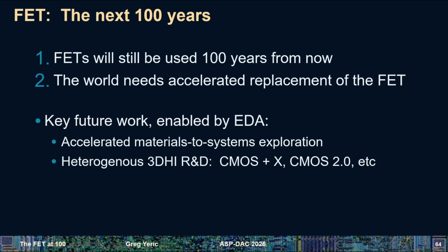At the same time I say that, the world desperately needs the acceleration of something better than the FET, because fundamentally, field effect means you have to put a voltage on a gate, and you have to bring the parasitic capacitance of all the wires attached to that gate up with you. That doesn't scale, and that's a power problem that you just can't solve when you have a moderately high voltage that you need to get to. So we need something that is lower voltage or fundamentally different than the FET.